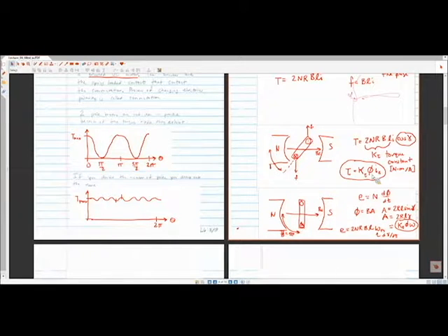And then I discussed how this torque constant can be expressed in a variety of different ways. Usually if it's a field actuated DC motor, that means that we have an electromagnet which creates the magnetic flux that acts on the rotor. Then it's K tau times phi. If it's a permanent magnet, they usually lump the torque constant and the phi together because that phi is constant. It's getting constant flux from the permanent magnets that are built into the system.